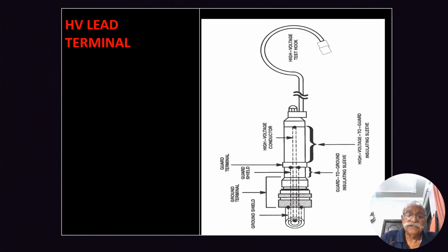The HV terminal lead plays a very important role. This lead should have minimum resistance, and it should have 10 kV insulation, because when the Cn tan delta test is done, it is done at the 10 kV level. This lead plays a very important role, because you have to make a very solid connection, and there should not be any leakage when this lead is placed on ground, or this lead should not have any leakage current through ground.